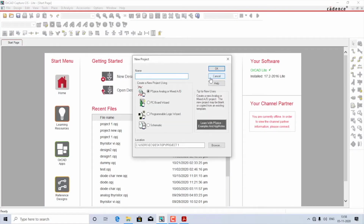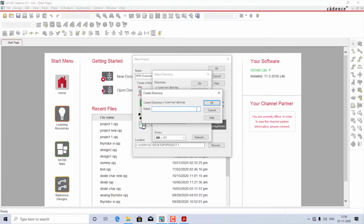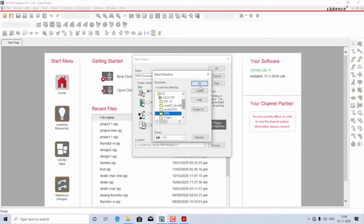I'll create a new project. I'll name it NPN characteristics. I'll make sure the type of the project is PSPICE analog or mixed AD, and I'll save the location of all the project related files into a folder. I'll create a folder on the desktop and name it NPN. I'll select that and then press OK.